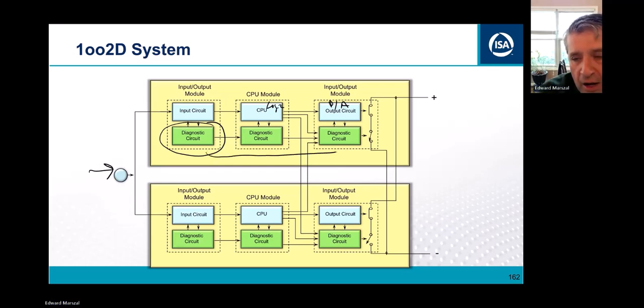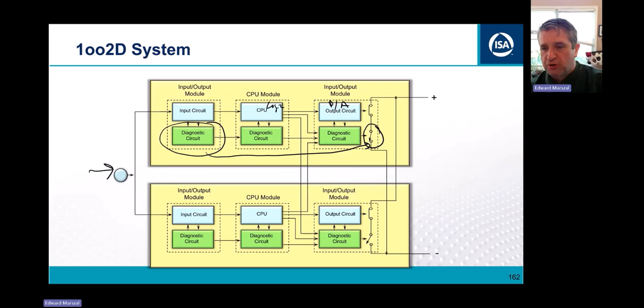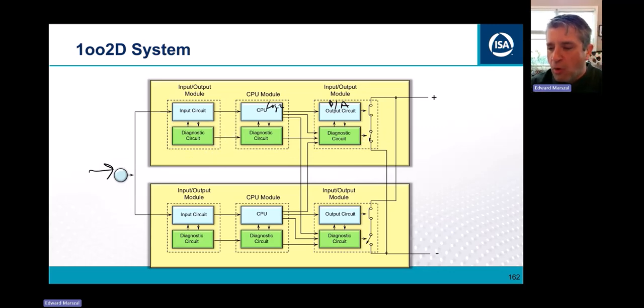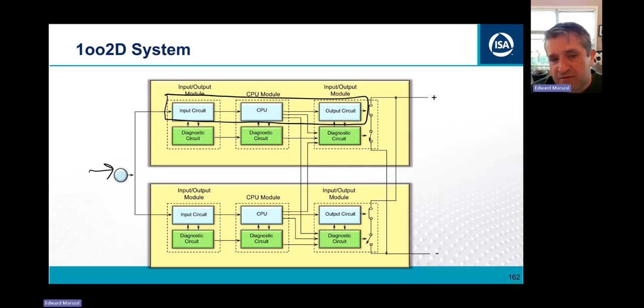And then in a modern system, the diagnostic circuitry will be able to open the circuit with its own dedicated separate switch. So what PLCs now are giving you is a ton more diagnostics and the ability to independently de-energize outputs, even though the traditional circuit that I showed you on the other slide is still sitting up here on top.